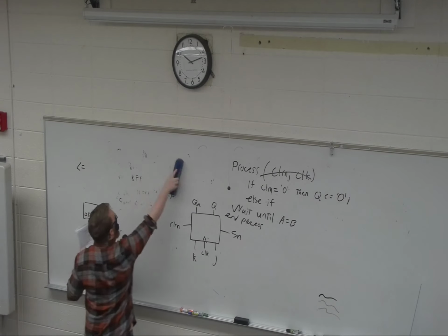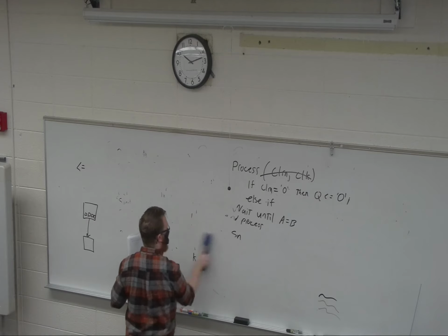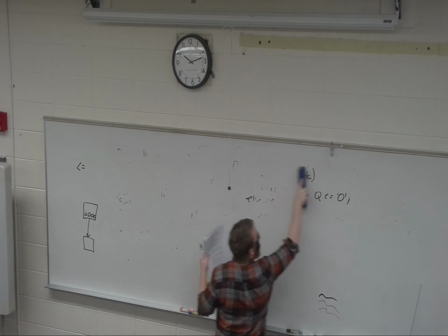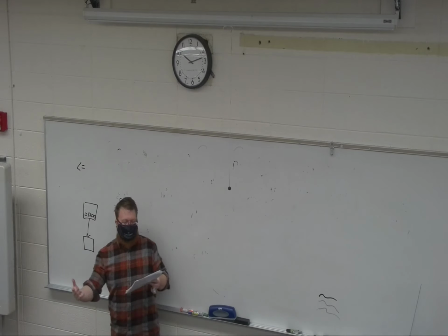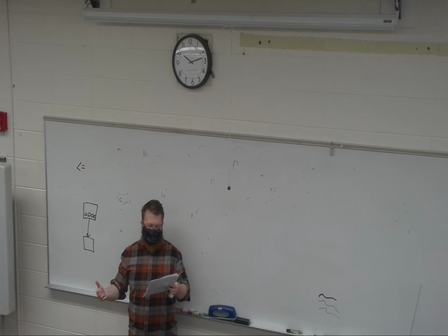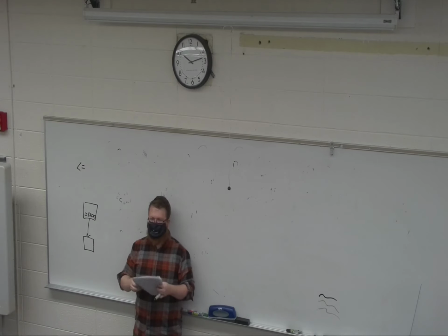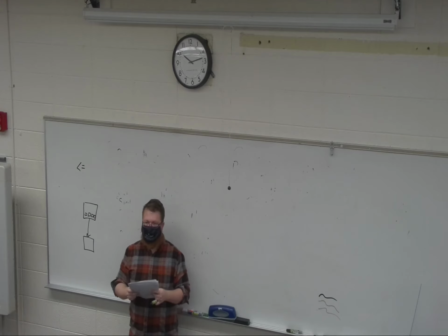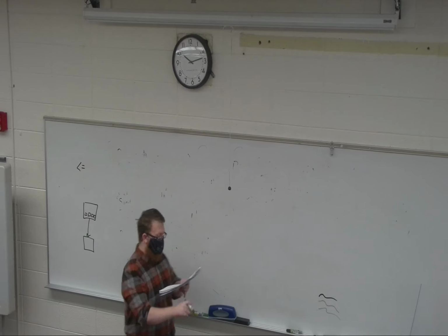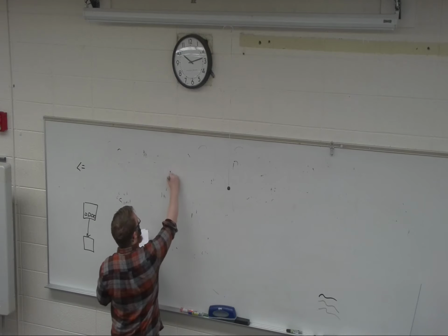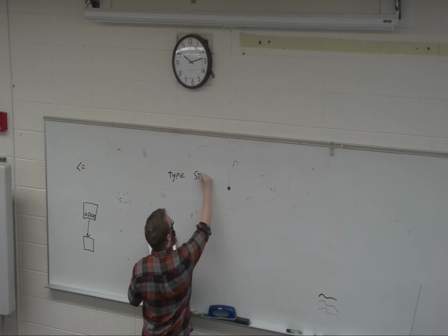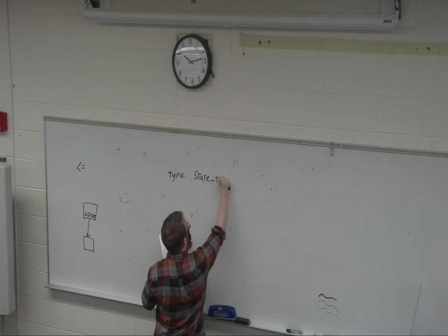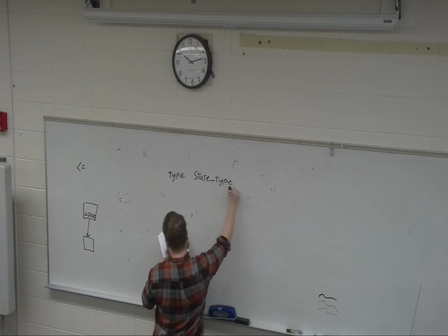But to understand those, we're going to start with some of the basics of Verilog. Not Verilog, VHDL. Gosh, sorry guys. On page 82 is a list of data types that you can use: bit, Boolean, integer, real, characters, and time. You can also create your own types of data, and the one that you'll use all the time, for shorthand, we're going to call it a state type for the moment.